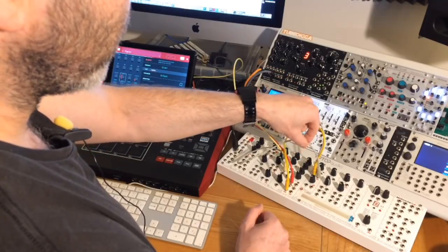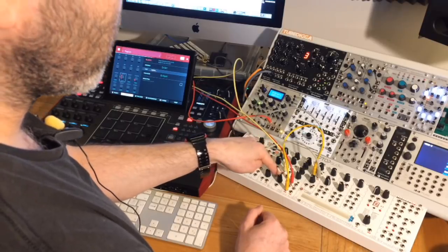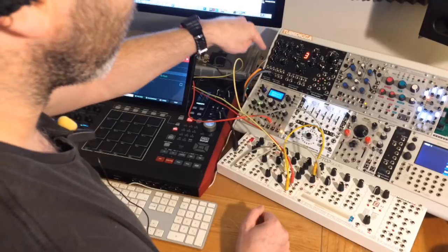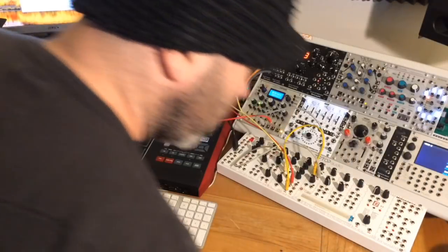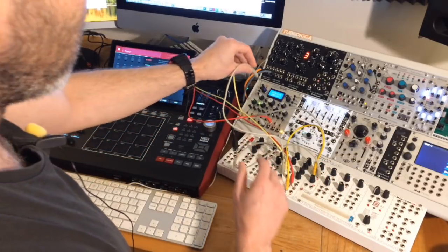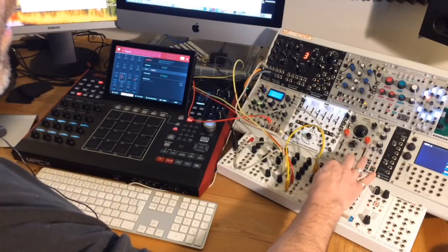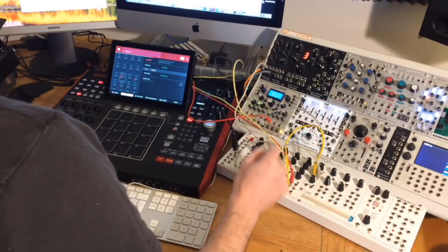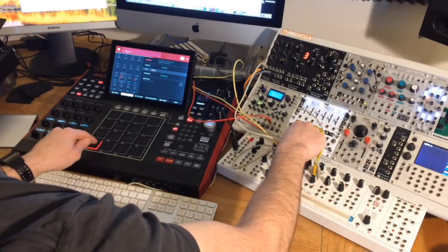So I've got the VCA going into the filter, and now the output of that filter, we can choose a low pass or a band pass. I'm just going to choose low pass, and I'm going to take that out and put that into the mixer. So I just need one more cable for that. Let's take this cable, let's go out of the low pass output port of that filter and put that into our mixer. So all we've done is bypass the VCA going straight into the mixer. We've bypassed that, gone into a filter, and now we're coming out of the filter into the mixer. So now we can control the filtering.